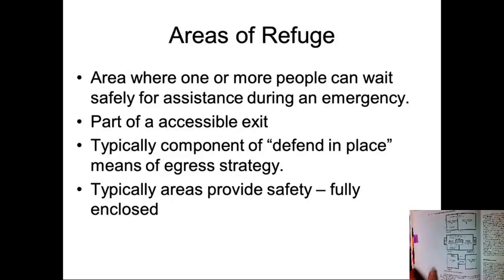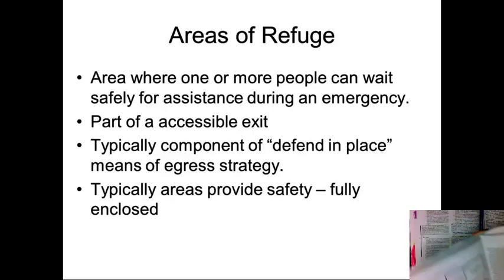Areas of refuge. That's an area where one or more people can wait safely and assist in through here. You're going to find this in areas of refuge in 1007.6 in your IBC code book. You've got to look through that and understand. It tells you exactly if it's near the elevator or the size of it within the stairway. Read that and understand it. It's typically also known as defend in place. Typically, areas provide safety which are fully enclosed.